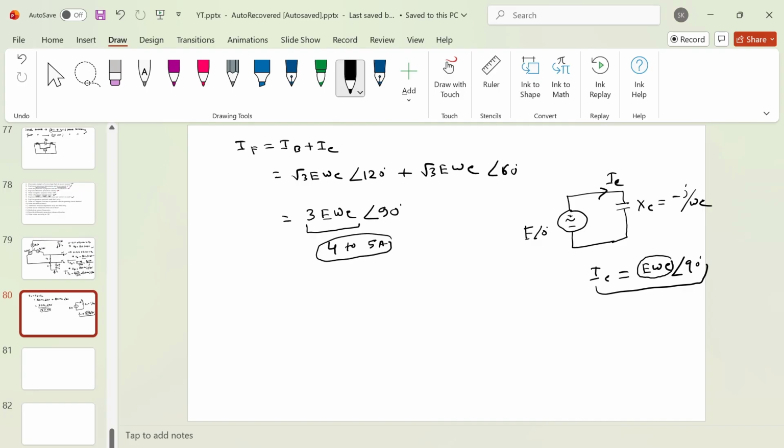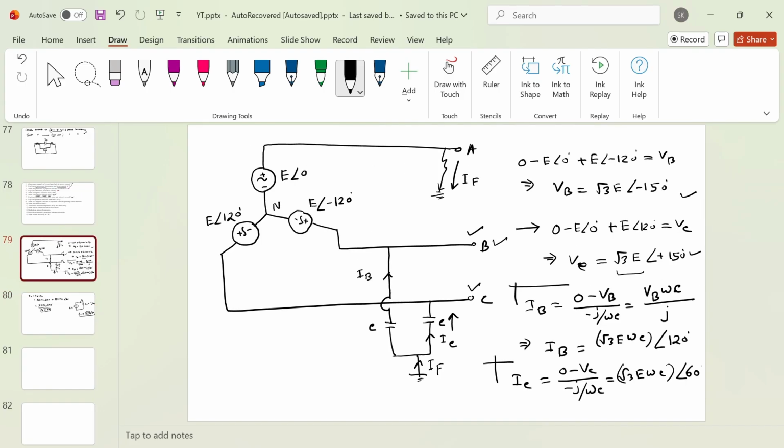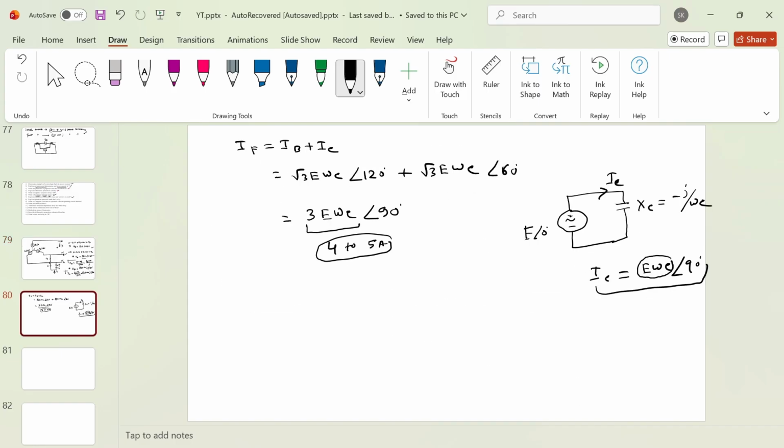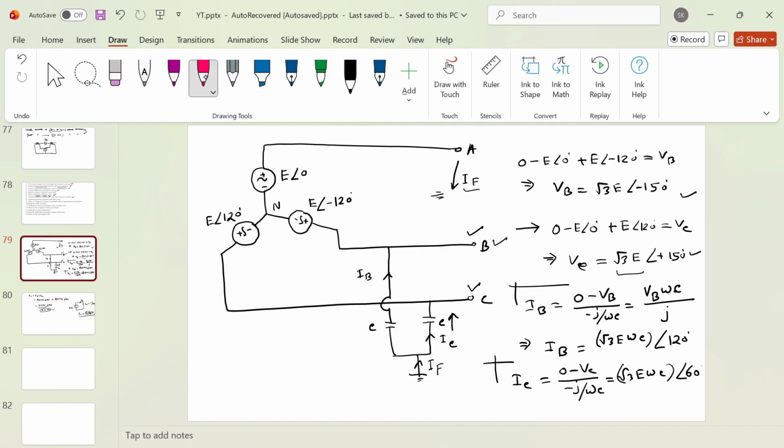And if this current magnitude reaches up to 4 to 5 ampere, then this huge amount of current is enough to ionize the faulty path. For example, you got some kind of fault here at any moment, and the moment you got the fault, the fault current will start to flow. But after some time, let's say you removed this faulty path, but since this current was around 4 to 5 ampere, this current basically ionizes this path.